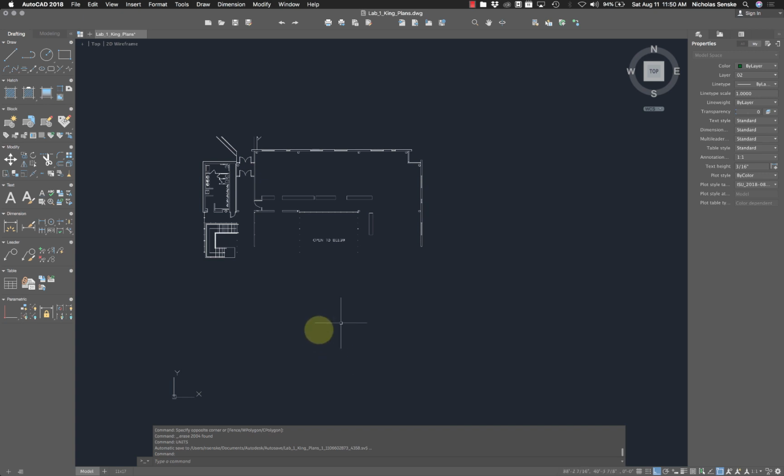The other thing that it's important to know is that when you're drawing in CAD, you're making a drawing that's in real space dimensions. So 3 feet is 3 feet. Even if the drawing you're going to print later on might be at a 1/4 inch equals a foot scale, or 1/2 inch equals a foot scale, or some scale. It's not the real scale, right? It's always going to be some kind of fraction of it.